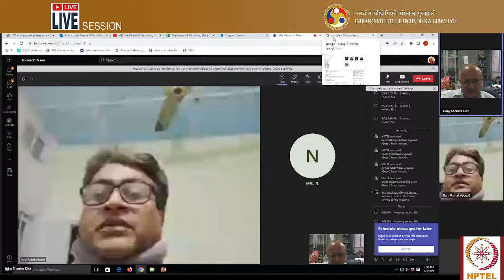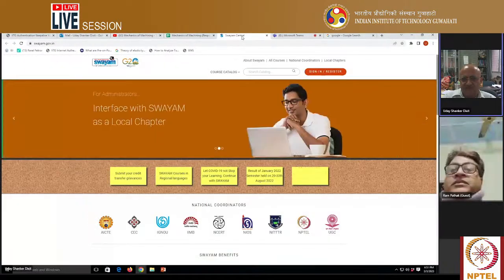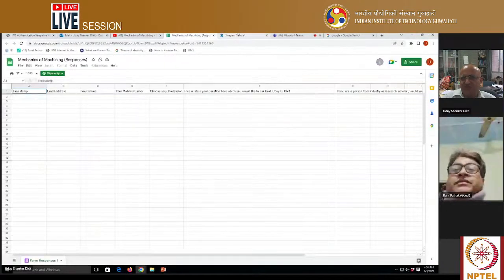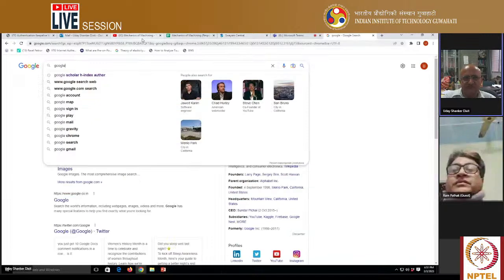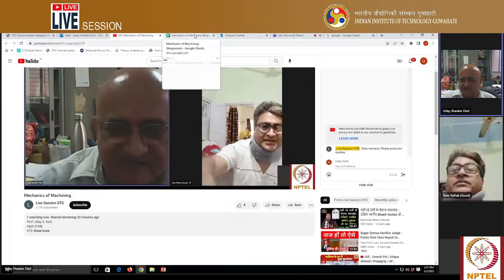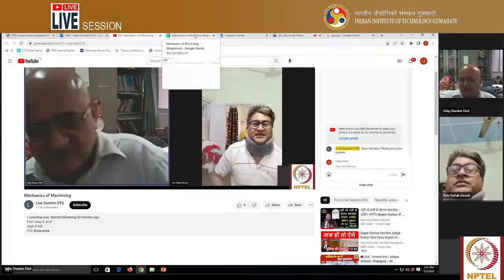This type of arrangement, this type of preloading, we do to minimize backlash. Otherwise there will be backlash. So that is called double nut compensation.